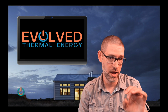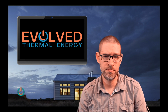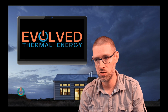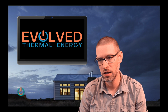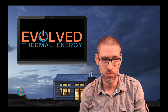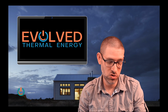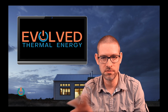Now, let's say my house was on propane. If we convert this house to propane usage, I can model that out to understand how much propane I would have to use for heating. That would turn out to about 4,800 liters per year. And if I convert that to kilowatt hours, that essentially equals 33,984 kilowatt hours. So there's that comparative there.